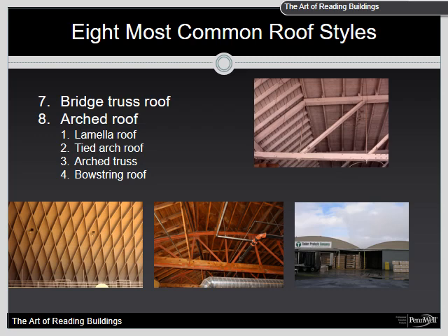Tied arch roof. Note, Chapter 3 featured a brief history on the arch truss. Although the tied arch and bowstring roofs are both arched, there have been different opinions regarding the nomenclature for these two roofs. The tied arch roof looks like a bow when viewed from the side, but it is not a true truss, as it lacks diagonal webbing.